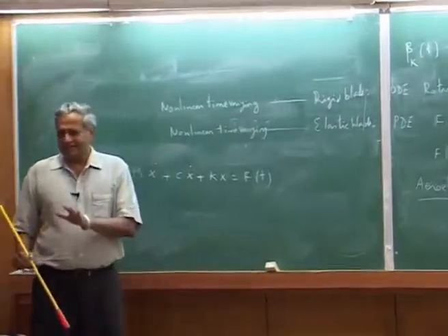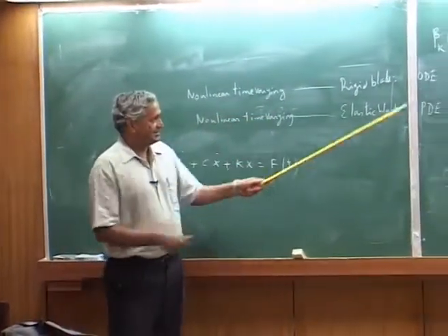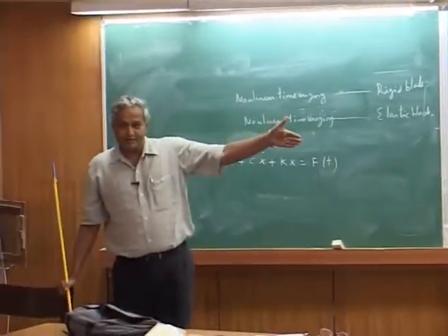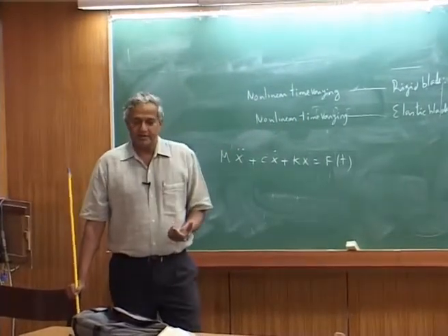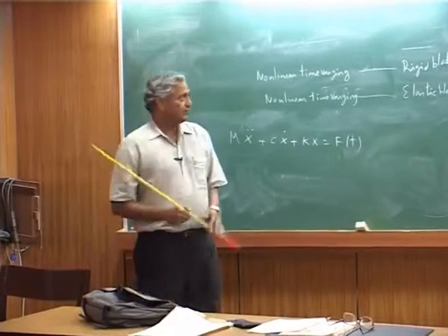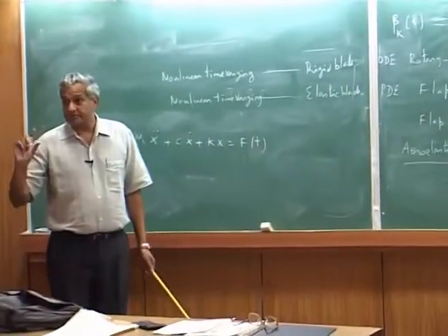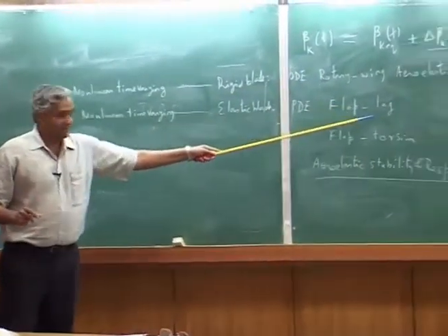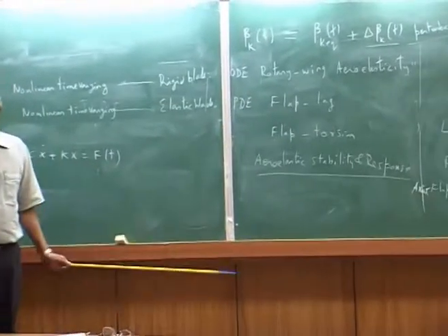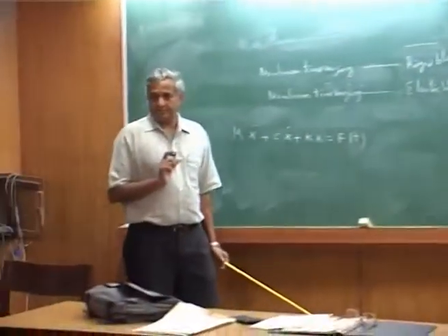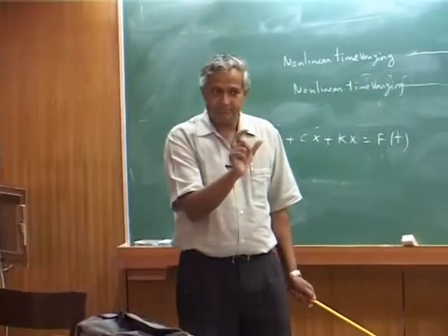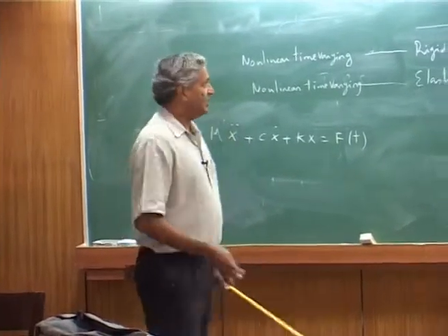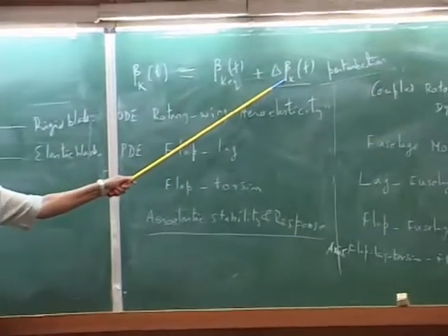On the other hand, you will say, hey, I am starting directly with a rigid blade. That rigid blade I assume, then I will get directly the ODE equation. Straight away I go to ODE. Now, in the ODE, how do I solve? So the first thing is all the degrees of freedom. The degree of freedom is flap, the degree of freedom is lag, if you are solving the flap-lag problem. Each degree of freedom has an equilibrium and a perturbation. So you always say flap, equilibrium, perturbation.